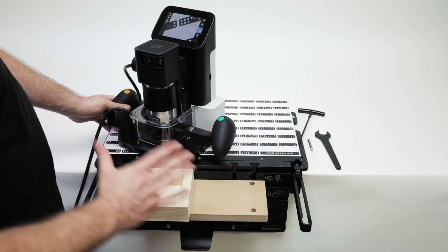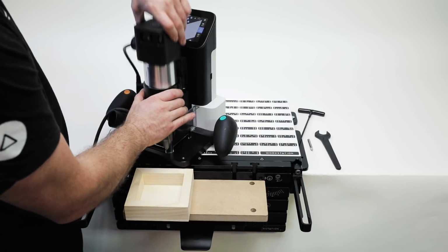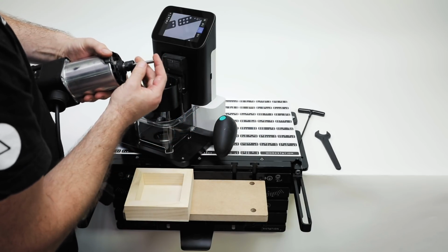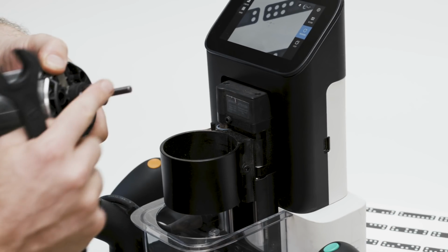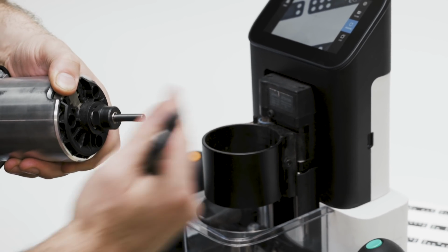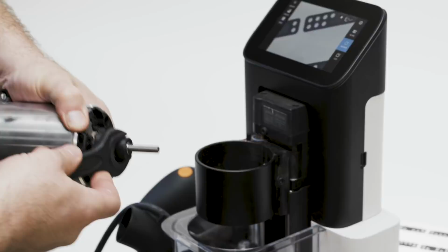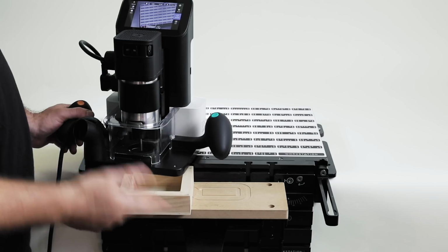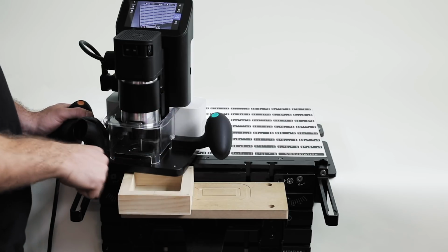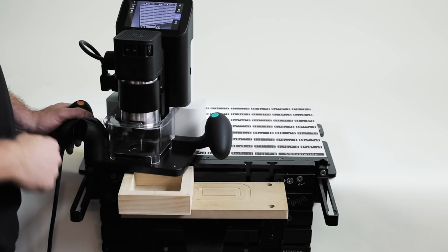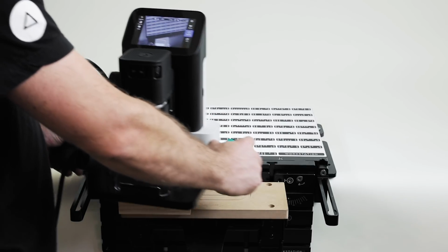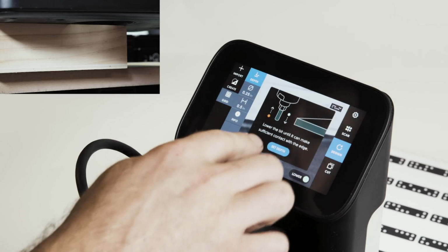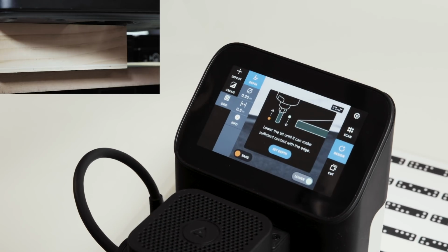First things first, we'll place an engraving bit inside the spindle, collet upside down so that the cylindrical shank is exposed. And we'll use that perfectly 1/4 inch cylinder to do our precision probing. We'll take an engraving cutter, put it in upside down, and tightened up. So we'll go through the motions of creating some grids. First we'll start with the standard basic grid where we just physically probe these 3 positions as seen in the info screen. Come over to this point, I'll go grid, new grid, and then we'll lower it.